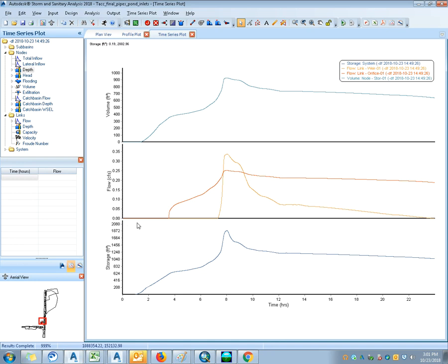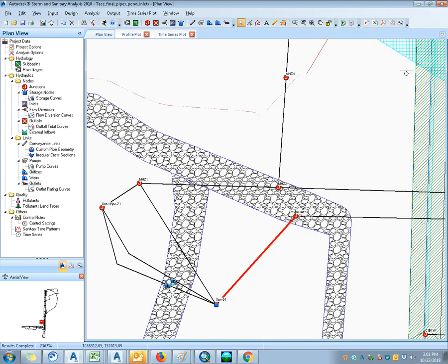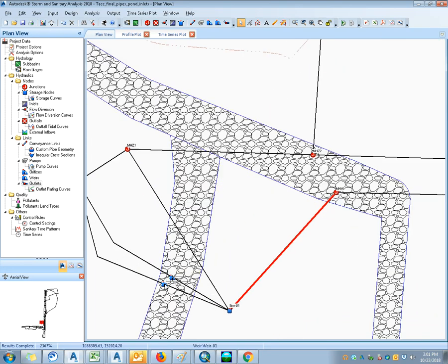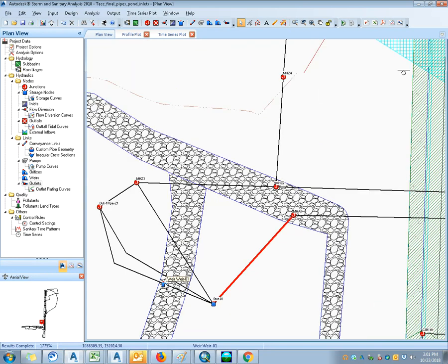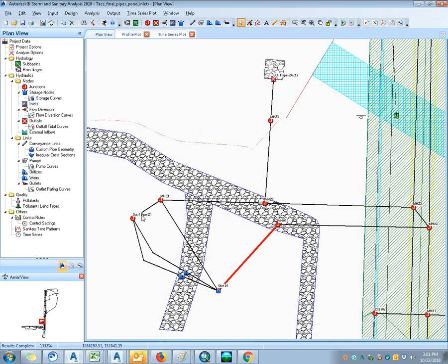I don't know what I'm doing here, but I'm trying to see what data I can get out for the pond. You still definitely don't have an overflow splitter set on the pond, do you? I just have an Orifice and a Weir. Did you add the Weir just now? No, one of these is an Orifice, and then one of these is a Weir. I basically just stole the data from Wim, so I have both of them in there. So that's your little notch basically in your pond. These are the low flow values, and then this is basically a high flow, like an overflow essentially.